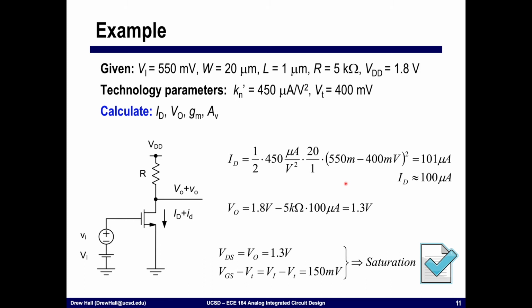We'll get really good at looking at circuits and reasoning out what region of operation we think they should be in, just based on pattern matching and familiarity with circuits. But always starting off with an active device and assuming that it's in saturation is usually a good bet. Okay? But we need to check this.